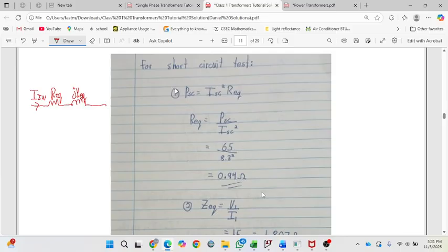So real simple. The first thing you calculate is, well, you have this equation here. From this equation, you can calculate your R, because P is equal to I squared R. That's the normal power equation, right? So you can calculate your REQ from here. So in this case, it will be 6528.3 squared, which was your current, and you get your REQ. And from that REQ, you can actually use that to calculate your XEQ.